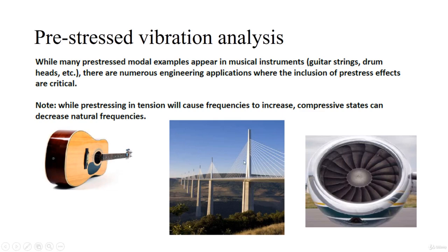Here also, for example, the cables that are used for attaching this deck to these pillars are also under some pre-stress. If the pre-stress applied is in tension, it will cause the frequencies to increase, and if there is a compressive state of stress, then it decreases the natural frequencies.